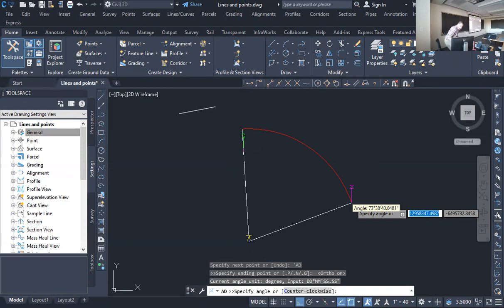So if you had 30 degrees, 45 minutes, 15 seconds, that's how you would enter it: 30.4515. It's not actually entering it as decimals of a degree because you've switched the unit base to read degrees, minutes, seconds. Notice how you can tell it angle left or angle right, depending upon if you went clockwise or counterclockwise.